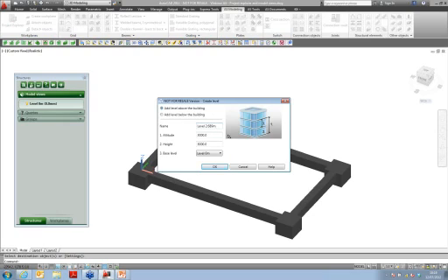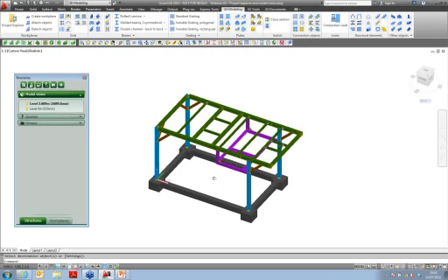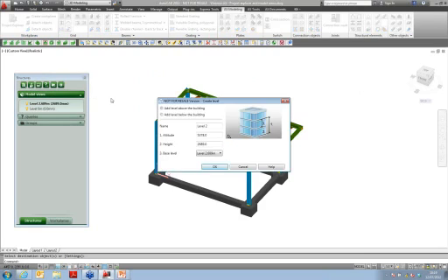2.69 meter. Okay, so I can specify here which level it is, press OK, and then I get my next level which is displayed automatically. I can continue like that and create another level just with a right click. Okay, I can specify a different height, for example 4.291 meter. Okay, 4.891. Okay, something like that.